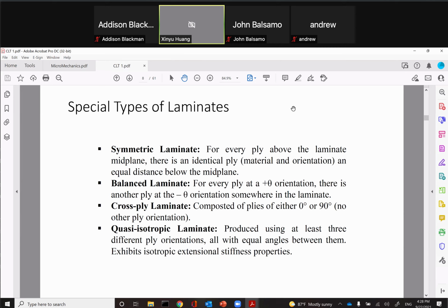So a quasi-isotropic laminate is one where, if you don't know its orientation, you cannot see where the fiber runs. You don't know the orientation. You cut a strip in any orientation, and you pull it in your tensile machine. They behave the same. So you can use these composite laminae to build a structure that behaves like that. It's called quasi-isotropic. There is no preference in any orientation.